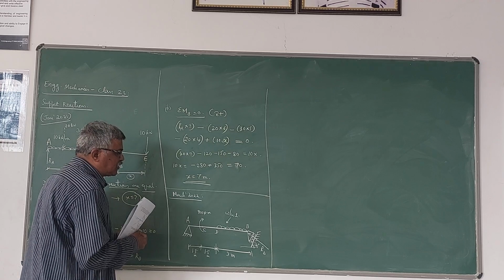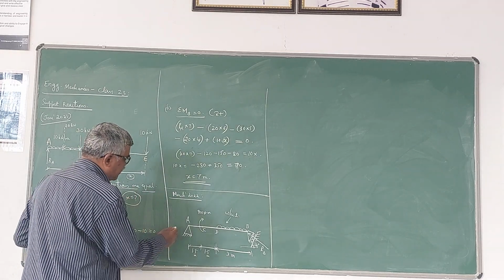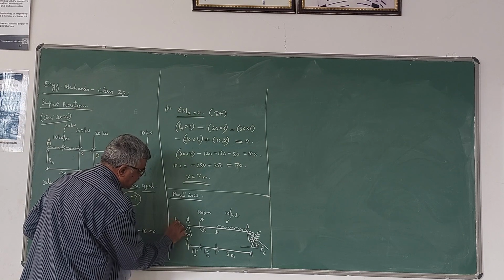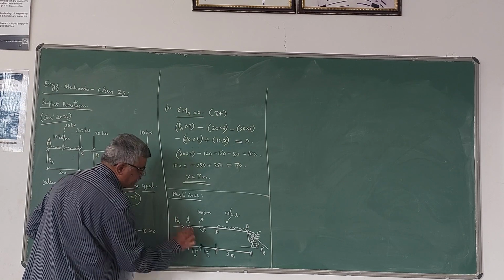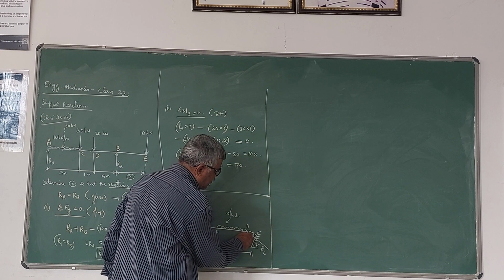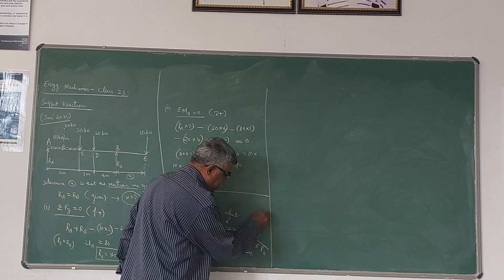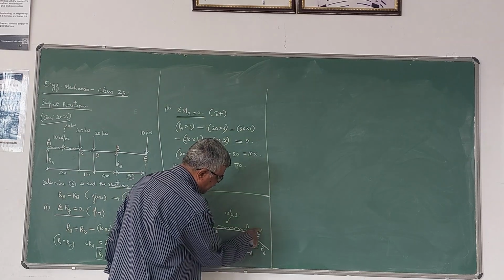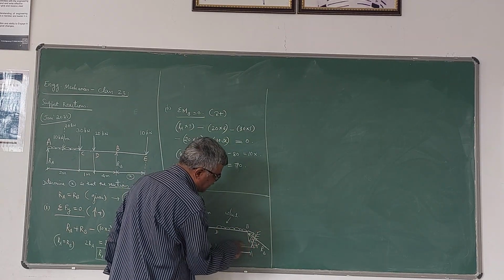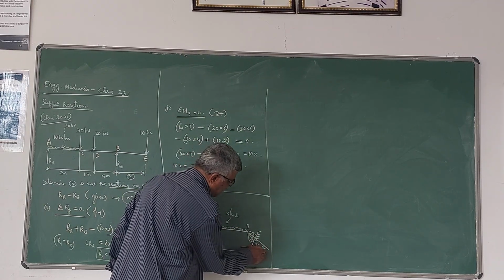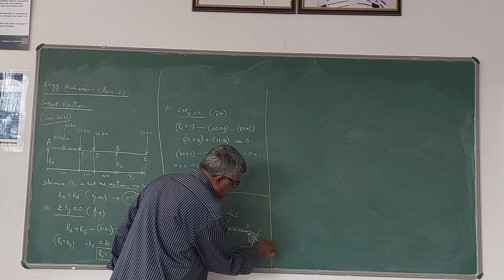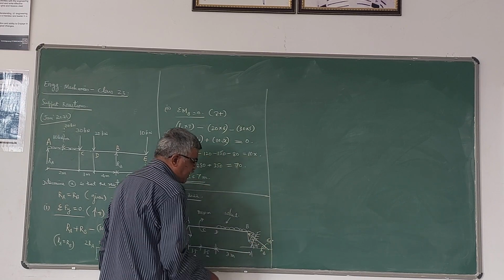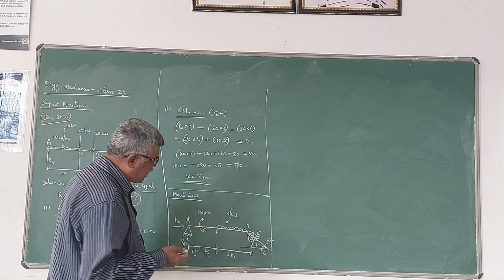So naturally we know that at the hinge end you will be having two reactions, HA and VA in general. And at the roller end you have only one reaction, which is normal to the plane of the roller, which is like this, making an angle of 30 degrees. This roller is making an angle of 30 degrees with the horizontal. Therefore, this angle will become 60 degrees. Please note that 90 minus 30. That means RB is making an angle of 60 degrees with horizontal.